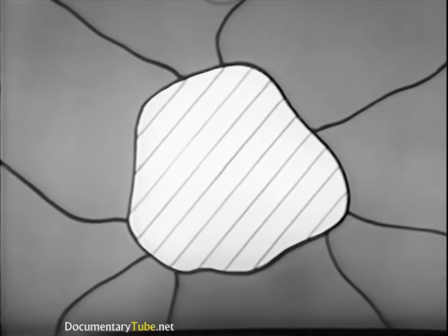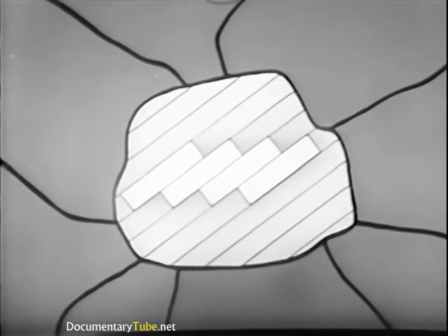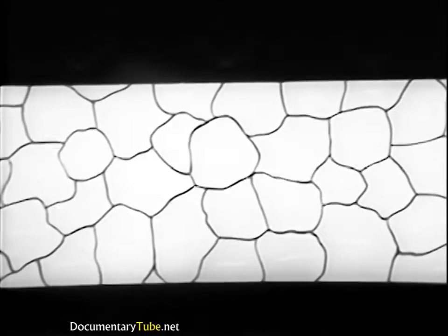Within each grain, the crystal blocks rotate to produce elongation. The deformation and rotation of any one grain is restricted by the differently oriented grains adjacent to it. These may also be rotating. Consequently, there is movement along the boundaries as well as along the slip planes.